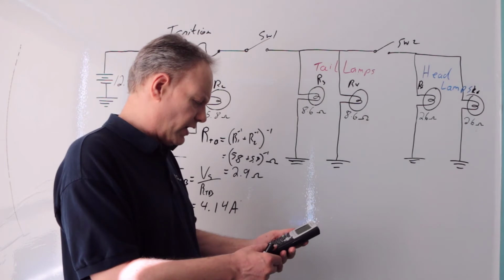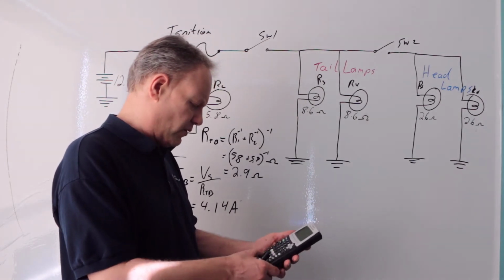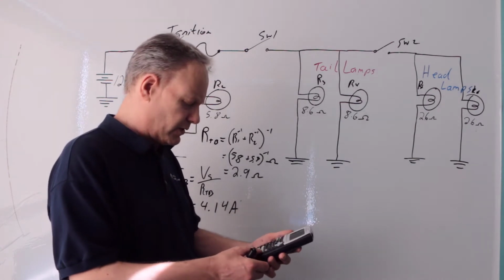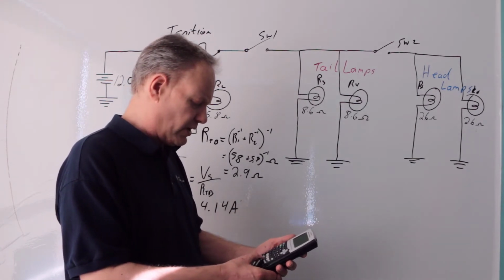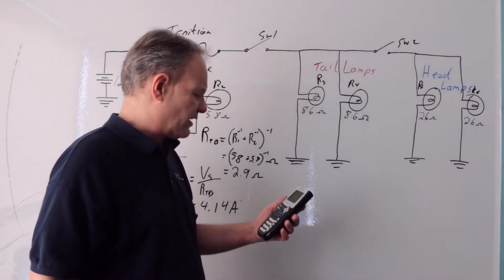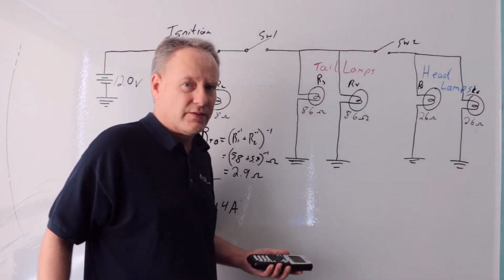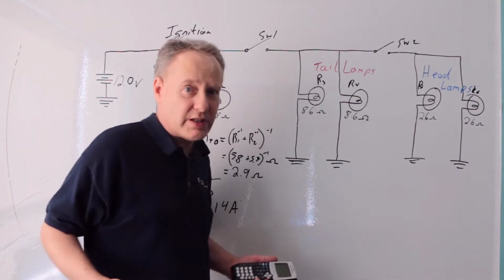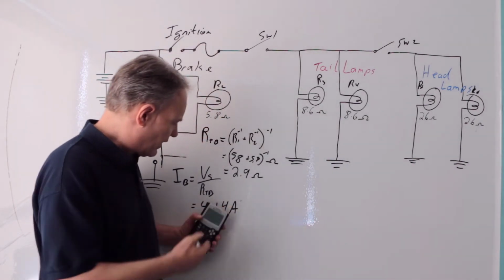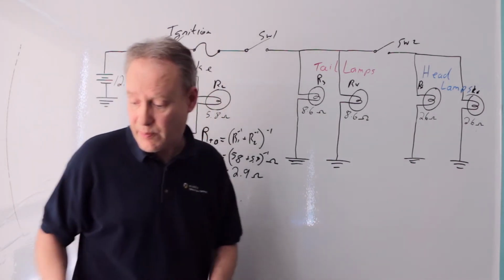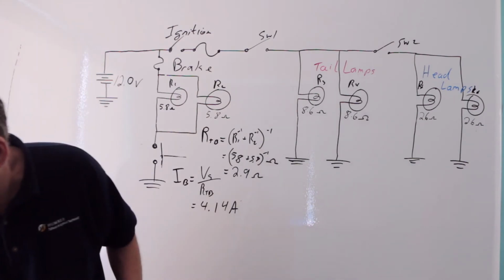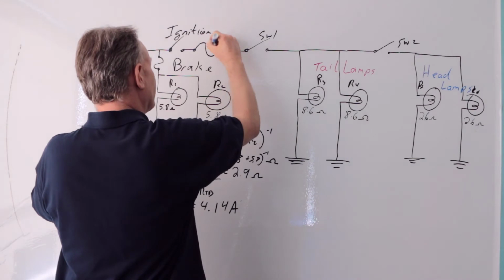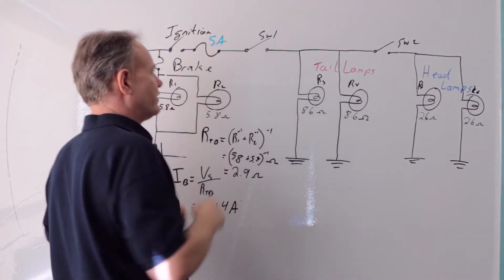Okay, you know what? I'm gonna go back to that. I'm gonna divide that by 1.15, so I get my original current, right? Then I'm gonna multiply times 1.35, and that's 5.5. So do you know what? If I get a 5 amp fuse, that's somewhere in between 15% over as far as the current goes, and 35% over. So that's perfect. So what I'm gonna do is I'm gonna label this guy. I'm going to put a 5 amp fuse in there.